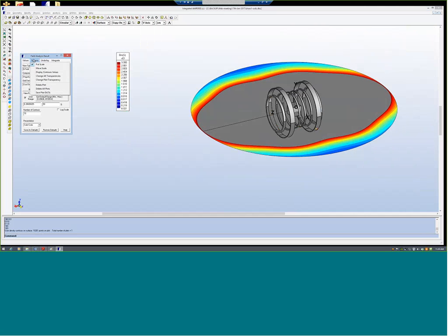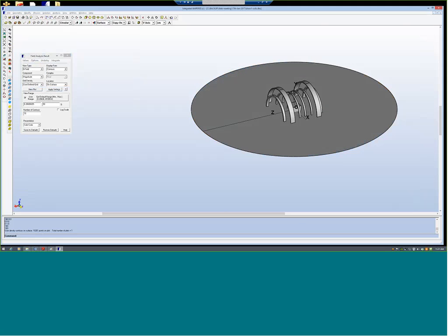Now what we do is create a shield which is 3 meters by 3 meters by 6 meters. So along the axis we will put a shield length of 6 meters, and along the cross section, in the x and y direction, we will use 3 meters. A 3 meter square shield we will construct. Option: delete all plots.